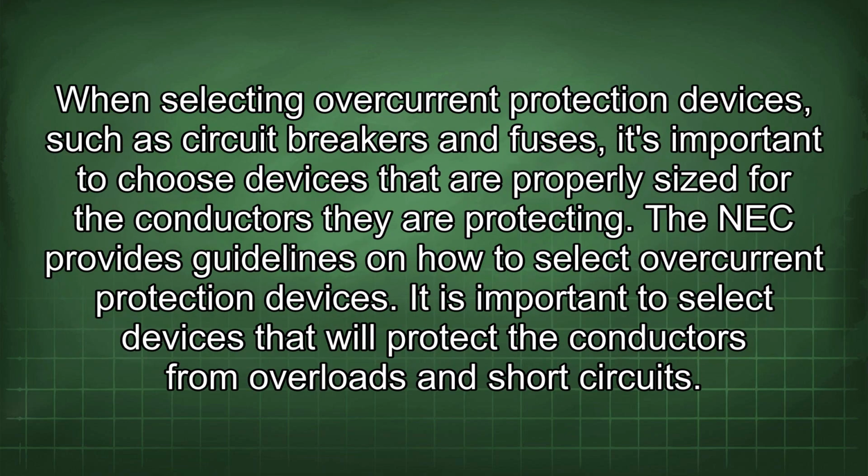When selecting overcurrent protection devices, such as circuit breakers and fuses, it's important to choose devices that are properly sized for the conductors they are protecting. The NEC provides guidelines on how to select overcurrent protection devices. It is important to select devices that will protect the conductors from overloads and short circuits.